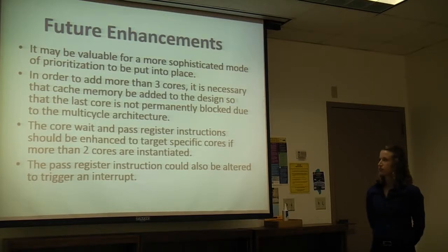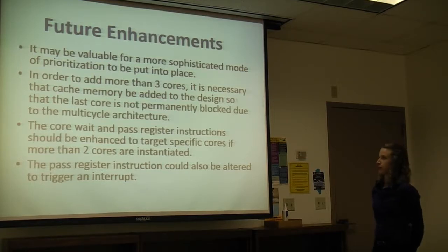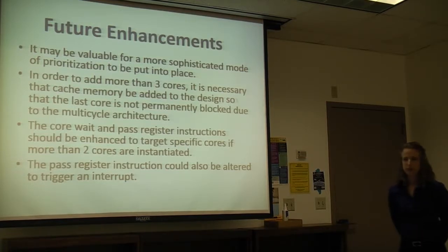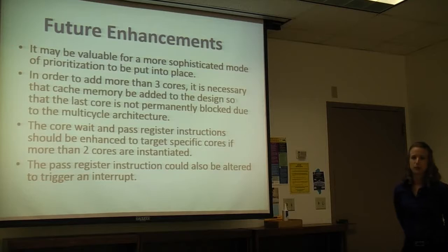Another thing is if we do add more than 3 cores especially, it's absolutely necessary to add cache memory because of its multi-cycle approach to architecture. Without that, the last core would pretty much never execute because the fetch state always reads memory. It would just have to wait.